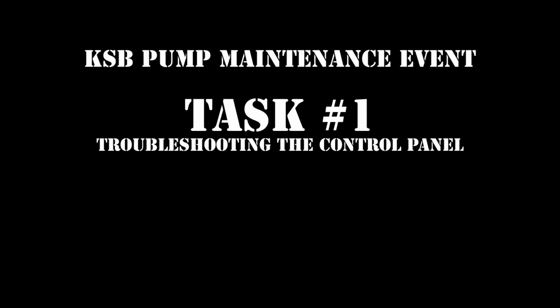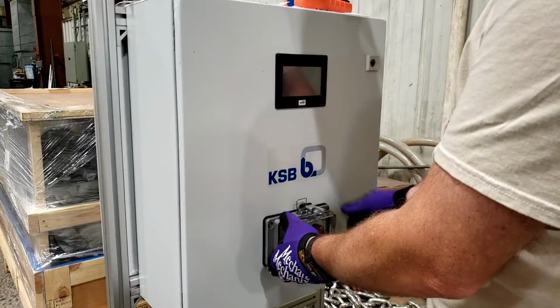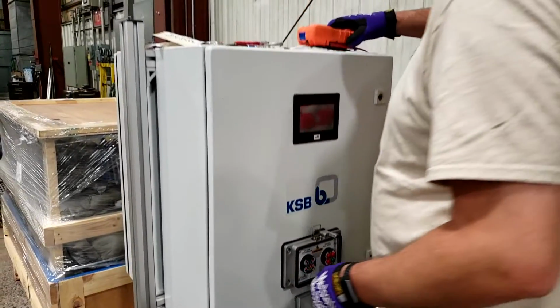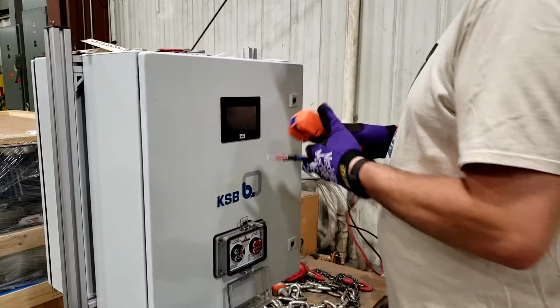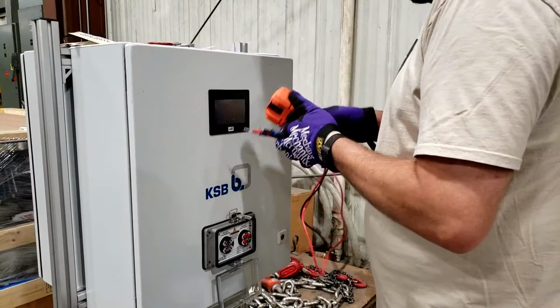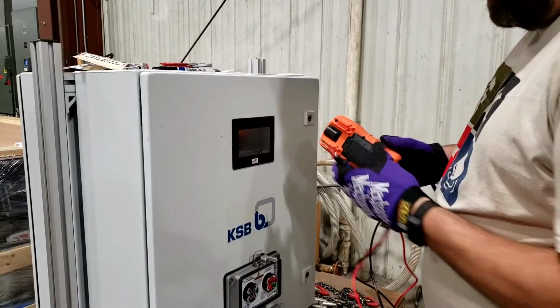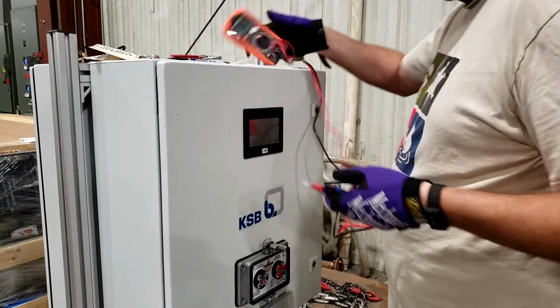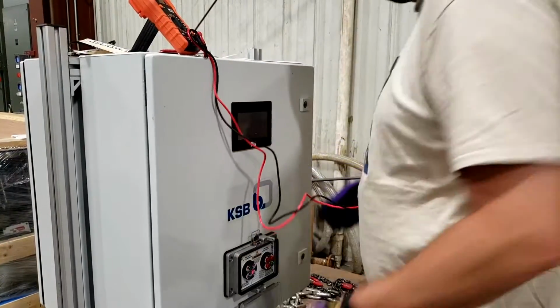KSB Pump Maintenance Event Task 1 will be troubleshooting the control panel. We will go to the voltage test station and confirm that the power lights are on and visible and lit up red. We will communicate out loud the voltage present at the pump station. We will then open the door to the voltage test station.